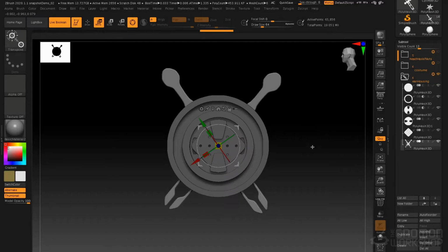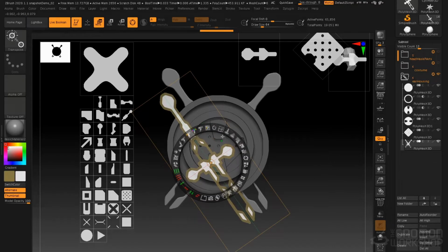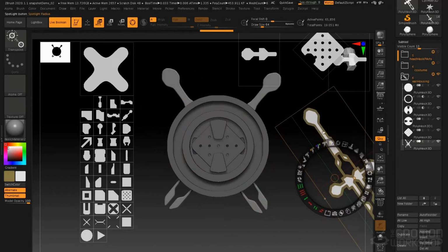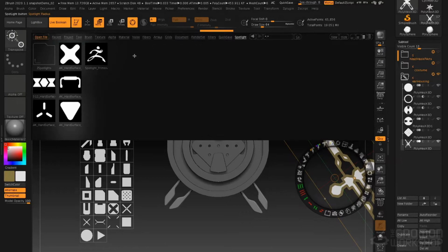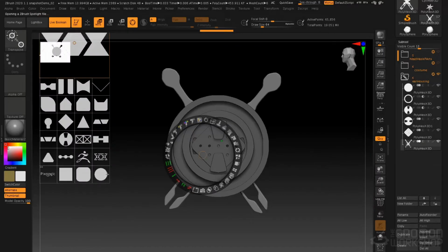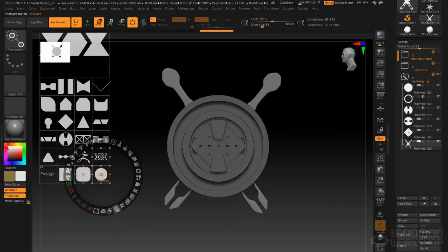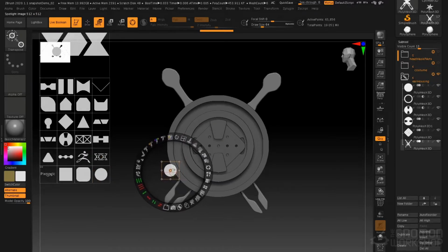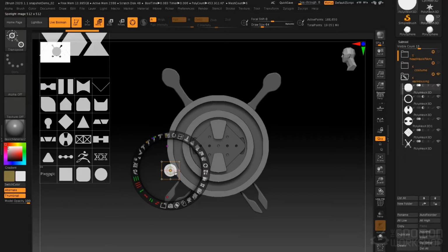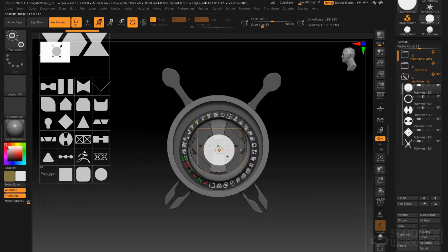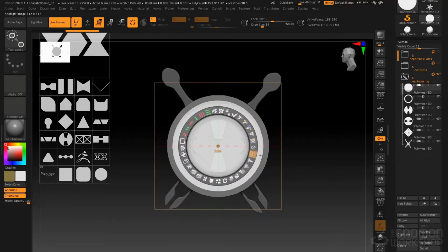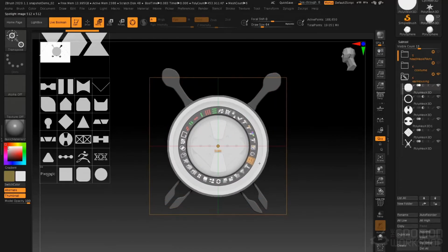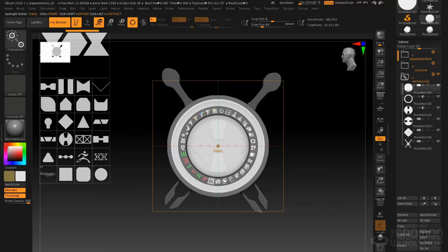So to do that, I am going to create a new piece. Let's go ahead and move this off to the side here. And let's go back to our original spotlight where we had our circle. We'll select this and duplicate it. I'm going to snap to the image center here and make sure that my original poly mesh is selected. Let's scale this up, and then we will snap that to the image center. Scale that up. And then, of course, we've got our frame button here.